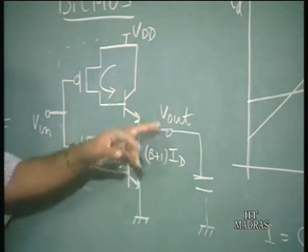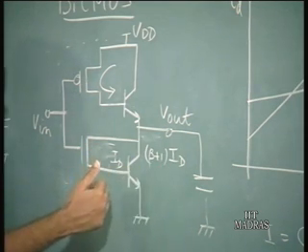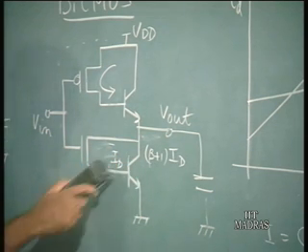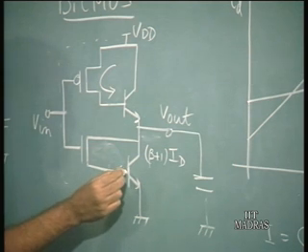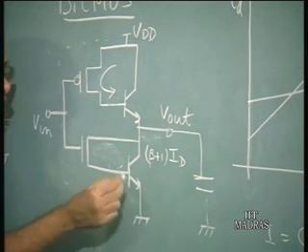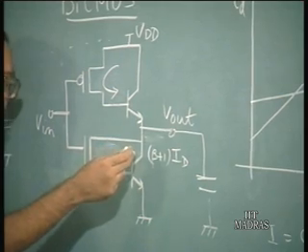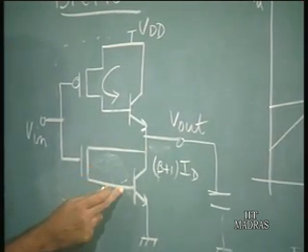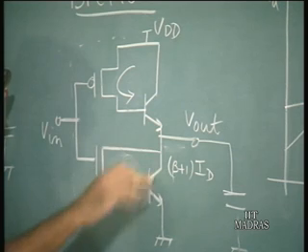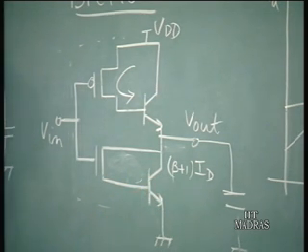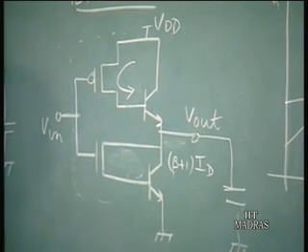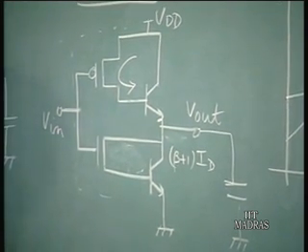Okay. Also, similarly, when the output capacitance is going to be discharged, the current flows through the bipolar transistor as well as the drain current of the MOS. Now, here again, the base voltage of the bipolar transistor has to be around 0.6 to 0.7 volts. When the output voltage falls to a value close to 0.6 volts, the collector voltage becomes equal to 0.6 volts. It cannot fall any further because then the base emitter voltage is going to be below 0.6 volts, which means that this bipolar transistor is going to draw a very small current, and the discharging becomes extremely slow.